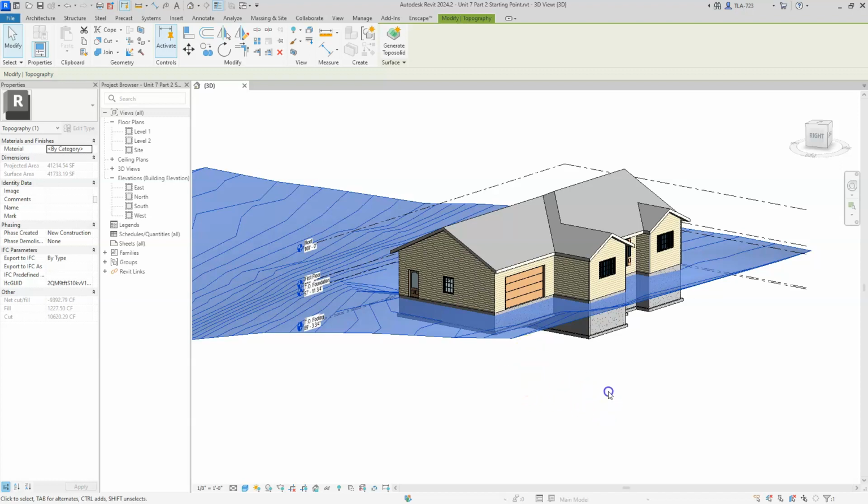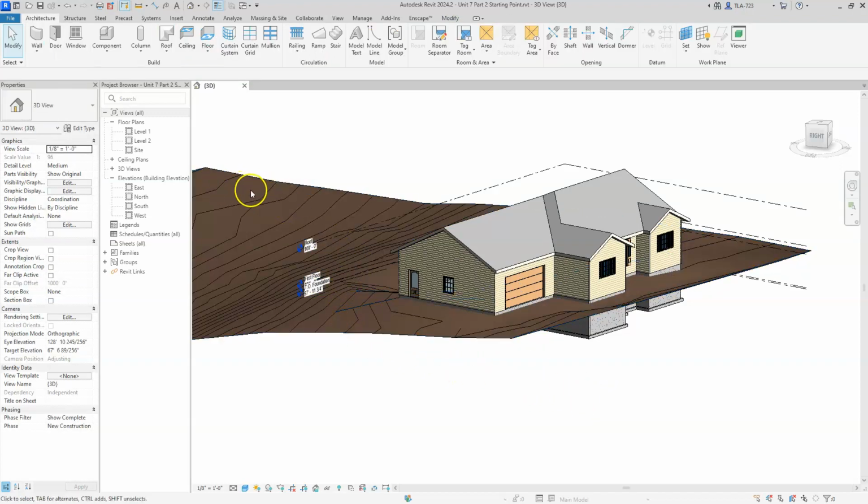We're also going to be exploring some different ways that we can change the surface once it's created and once we have it where we want it, both in terms of the color and also the materials that we're applying to that surface. So we can do things within or on top of, sort of like painting on top of the topography. Instead of creating separate elements like a sidewalk or a driveway, we can actually just color the topography to look like concrete in just certain areas.